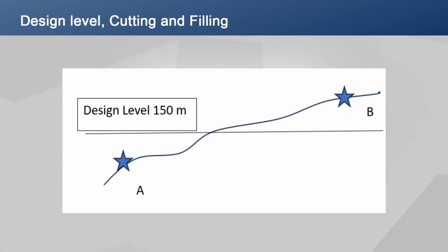Now, how can we proceed for measuring the earthwork? To accurately calculate the earthwork, the entire area must be divided into a grid system. At each corner of these grids, we will determine existing ground level using surveying instruments like auto level, dumpy level. The goal is to compare this measured level with the desired level of the ground.